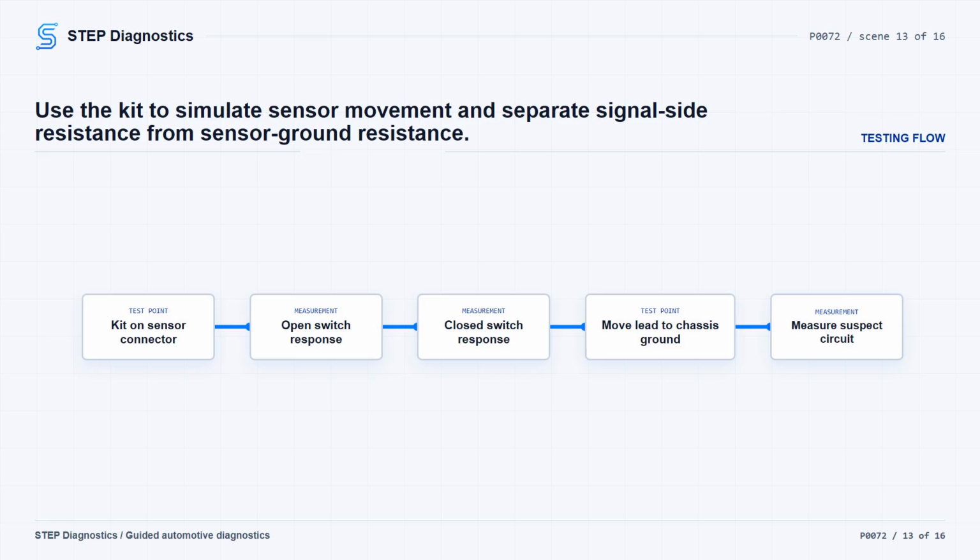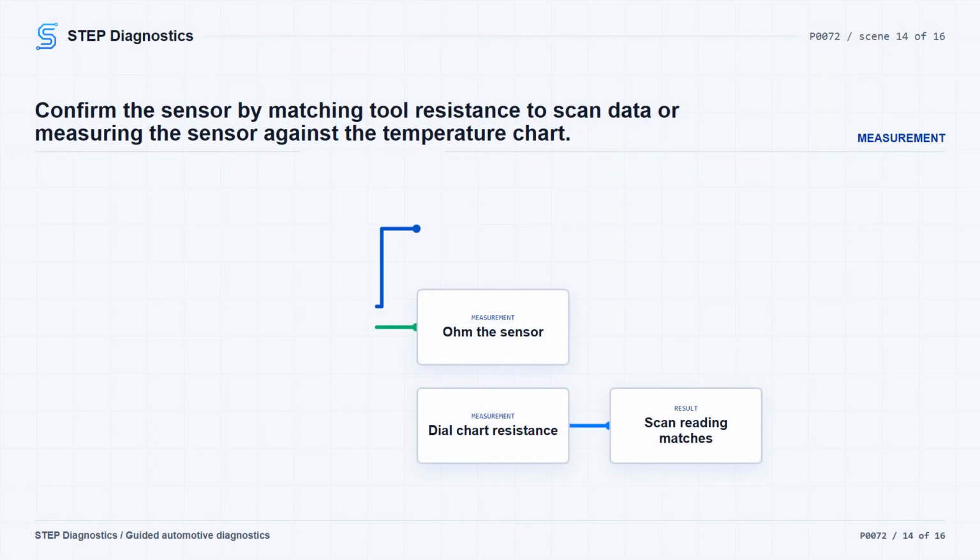Confirm the suspect circuit issue by isolating that circuit and measuring resistance between the sensor and ECU harness connectors. If no resistance is measured, carefully check the connectors in that circuit path for spread or dirty and corroded terminals. If the circuits check good, verify whether the issue is with the temp sensor or ECU. Temp sensor performance faults often come from resistance in a circuit or a sensor that is stuck or drifted out of range.